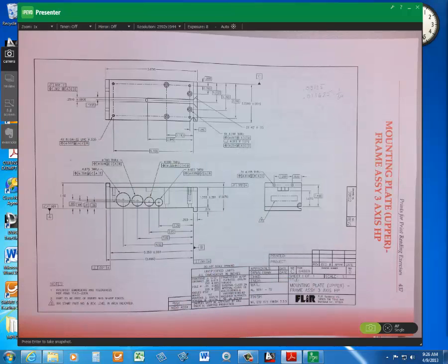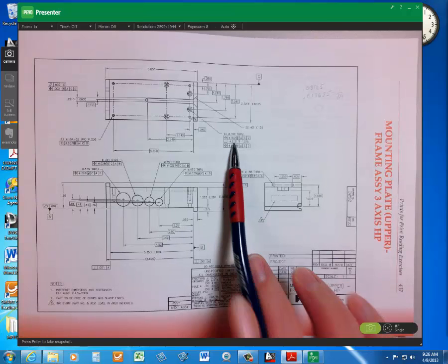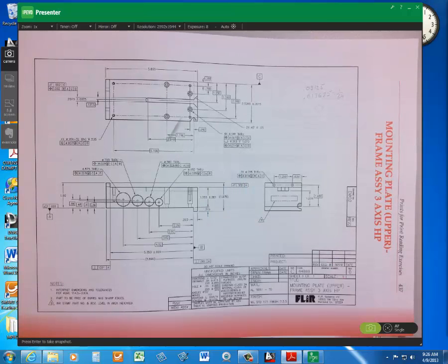None of them do. Okay, so we have to use this totally for our actual size tolerance for everything. So anyway, it's minus 1 thousandths, so it'd be 0.312, which would be the MMC of the counterbore hole. Then as we move toward the LMC in that little chart, we just add. So it starts at 14, goes to 15, 16, and then it jumps 2 thousandths, so 18.